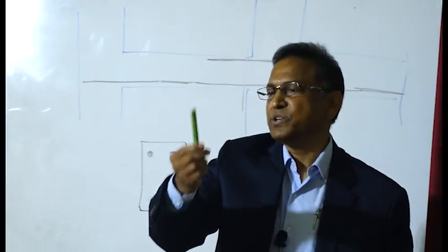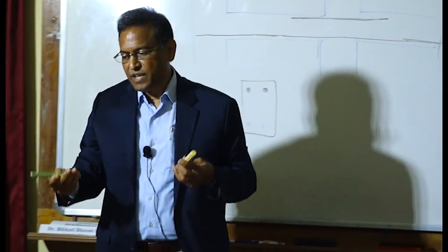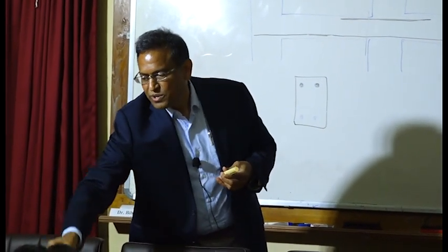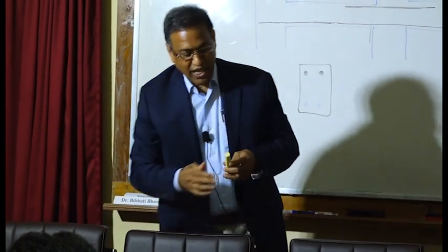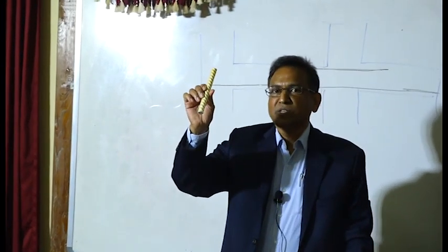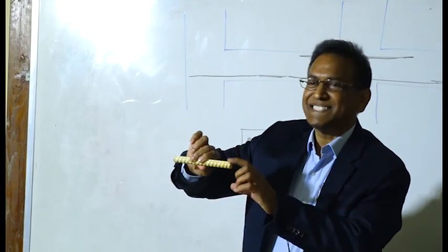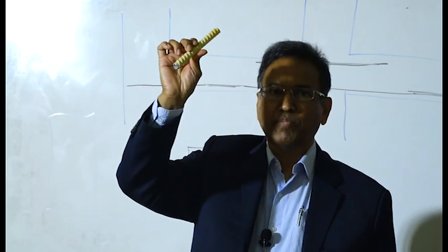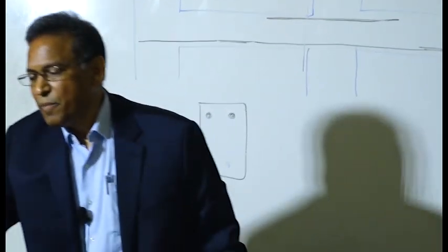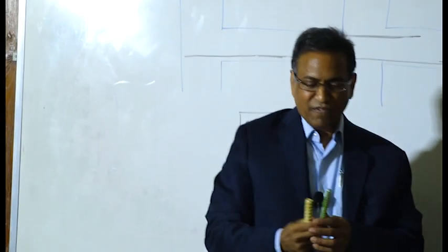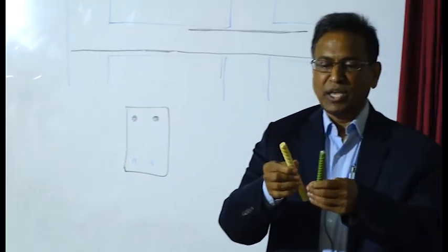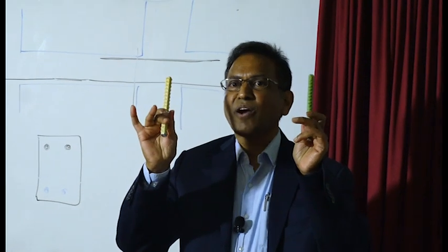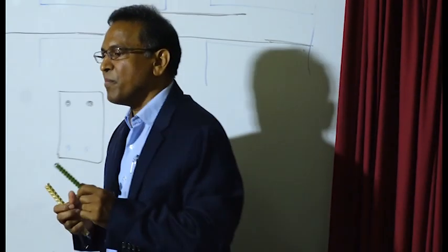Some of you have used it. You know what it is. And if you have not used it, take a look. And this one is dual coated bar. This is what I was talking about. It has zinc coat inside, and on top of it, it has also epoxy coating. Okay, so dual coating. But like our friends have highlighted, there are a lot of problems with epoxy coated bars. Primarily bond related.